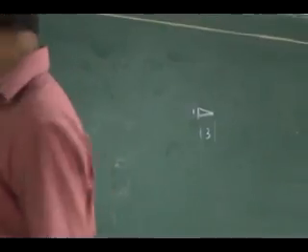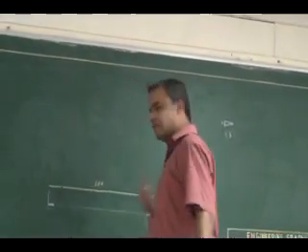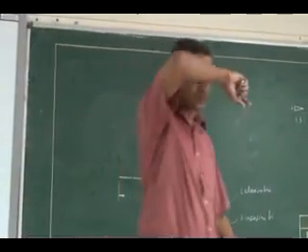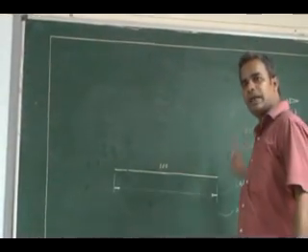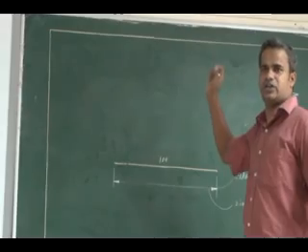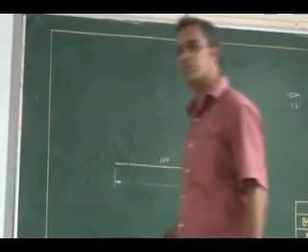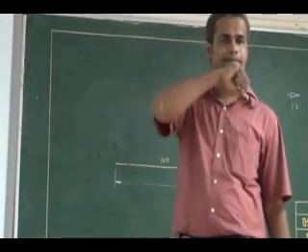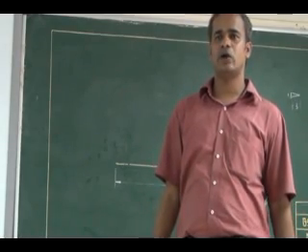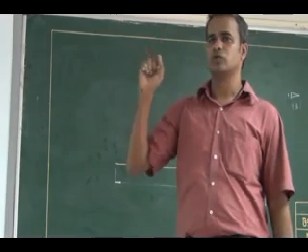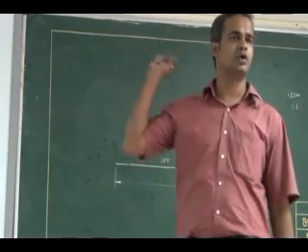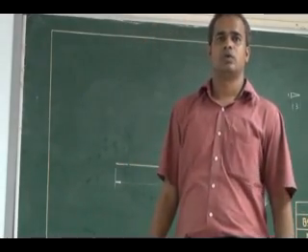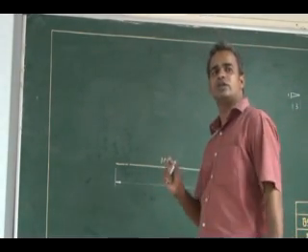So in dimensioning, I will have an extension line, a dimension line, then an arrowhead. Try to practice drawing a neat arrowhead. It is very much essential to improve the quality of your drawing. And the arrowhead should be fully shaded. In your class I have different arrowheads, but you show a shaded arrowhead with 1:3 ratio. So 1:3 in the sense 1:3 units.